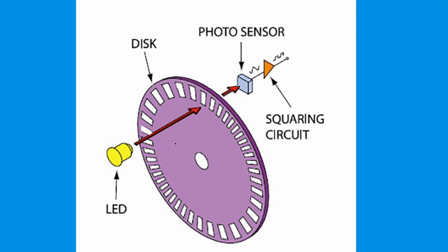One more thing you should know about encoders is counts per revolution. That's basically how many times an encoder counts, let's say a tick, for 360 degrees the motor turns. So let's say the motor starts here. If it turns 360 degrees, how many times would the light be detected? In this case, you would count up all of these, and that would be the counts per revolution.